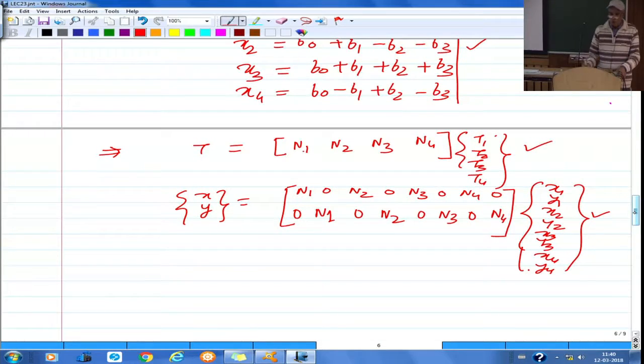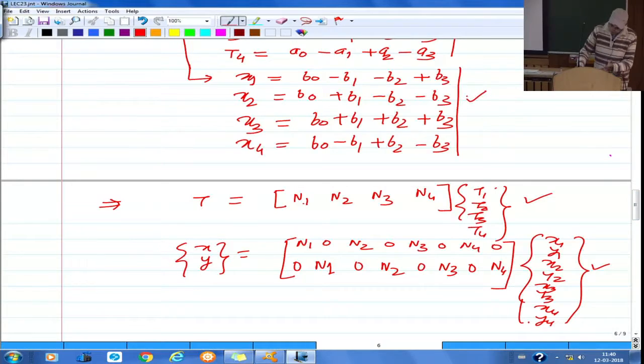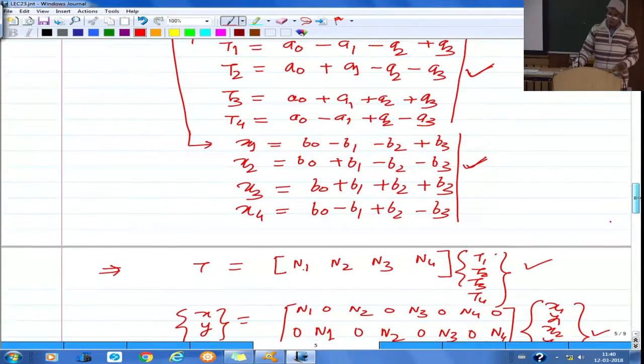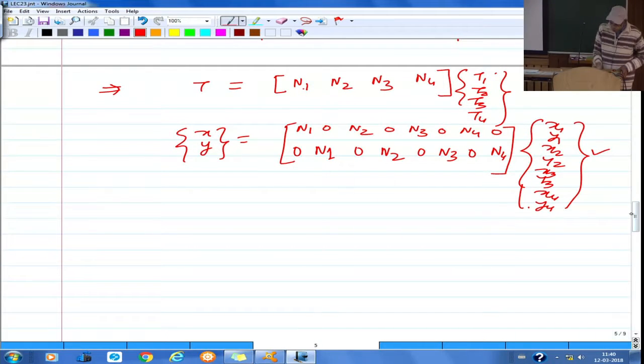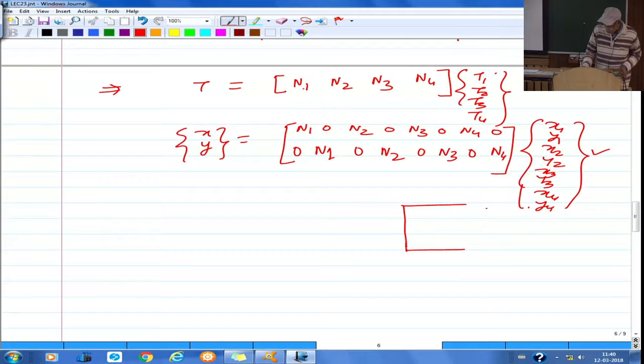Now these N1, N2, the way I wrote them for the rectangular element in the physical coordinate space, the same way you can write them, although the other step is, as I already told, to solve for all these constants in terms of the corresponding values of the variables at the node points, put back, collect the coefficients, and you get these shape functions. We can also write these shape functions directly, and keep in mind that these shape functions are going to be in terms of xi and eta. That means the interpolation functions are written directly, explicitly in the natural coordinate space.